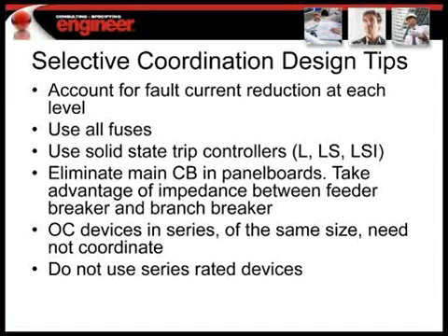Another important tip is to use circuit breakers that have adjustable trip settings. And then eliminate redundant circuit breakers that are in your system. Two breakers that serve common loads don't necessarily have to selectively coordinate and quite often can be removed from your system. And then avoid using series-rated devices. This is a matter of two circuit breakers in series used to provide enough AIC rating for the short circuit that might be available in your circuit, so avoid using those.